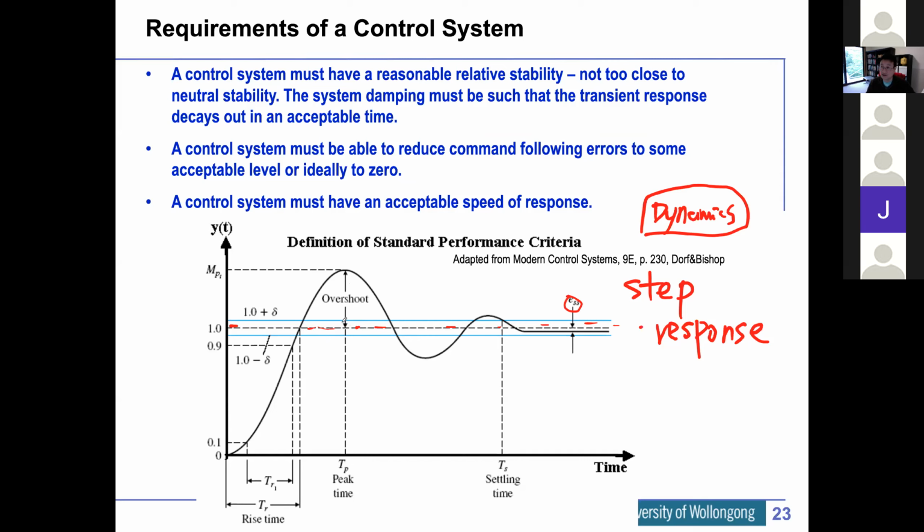That's overshoot. If we set it as 1, we don't want it to go to like 100 and then come back. Okay, we want it to go only a little bit over. That's overshoot. And the third thing we want is the rise time. So we want the system to follow the input quickly. We don't want to take ages before the system output follows the input.